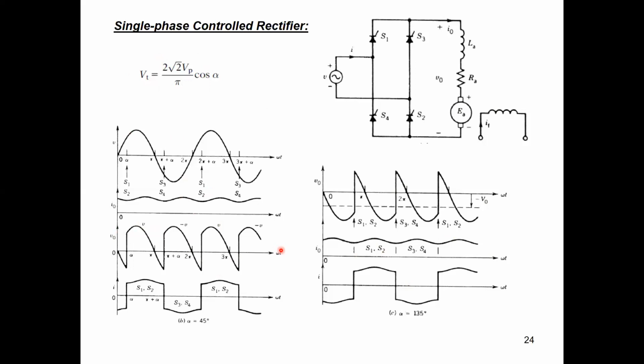So we can start the waveform from alpha and integrate up till pi plus alpha to the sine wave. So it will give you the average area at this part. So if we get the average area at this part and divide it for one complete cycle, it will give you the average value. One complete cycle means the instant of repeating the signal.